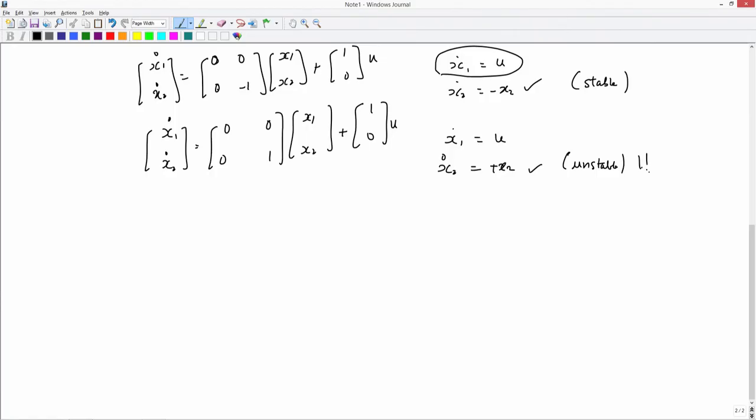So, there is some hope when the system is not completely controllable if and only if the uncontrollable part is stable by itself. Here I could do nothing with the system, because whatever smart kind of input I choose, my x2 is still unstable, which means that the overall system is unstable.